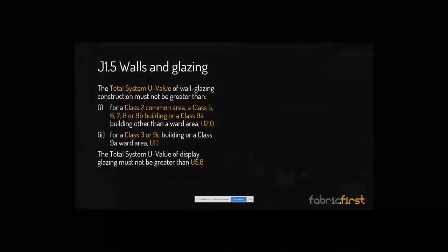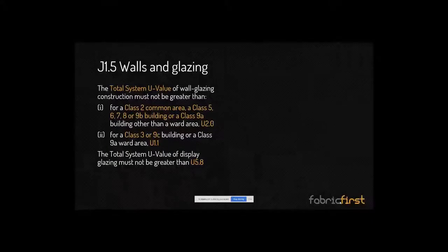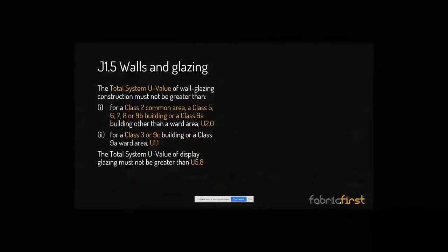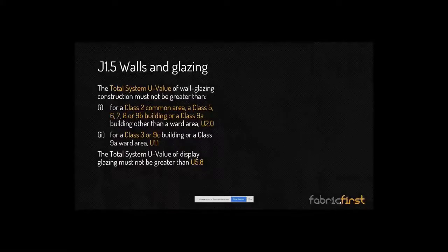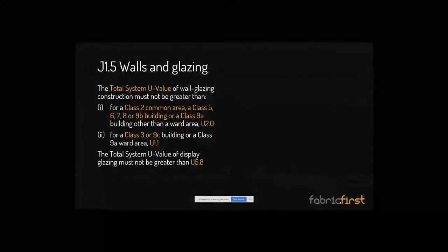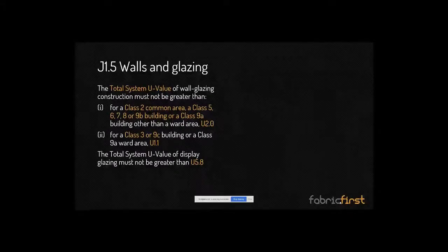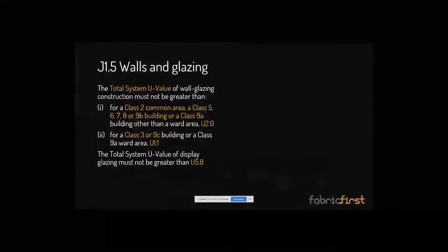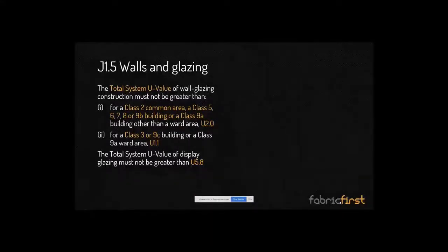Things are changing though in regards to this, and importantly they are choosing to include the wall within the system. Previously it was literally a bit of glazing, a frame, a bit of glass. Now they're doing the frame, the glass, but also the opaque area, combining them all into one in order to establish a value that represents both. In this case, I've aimed to simplify this because we'd be looking at too many numbers, so I'm just going to represent Melbourne here.